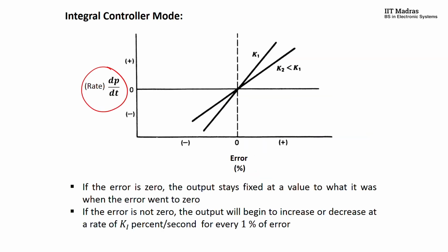But you can see that the proportional controller problems are resolved here by automatic reset. Because as long as the error exists, the integral controller keeps integrating either upward or downward to make the error 0. So there is no need to adjust this P0 term to a different value every time. That's called automatic reset. This would be more clear when we deal with the PI control loop. Fine.